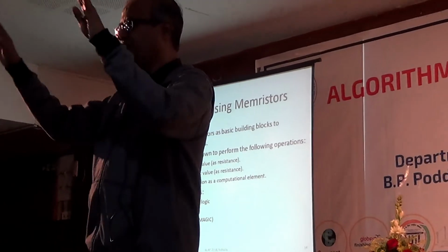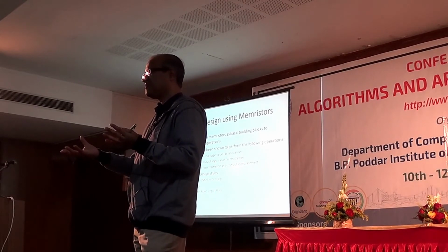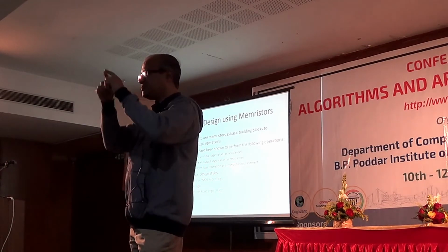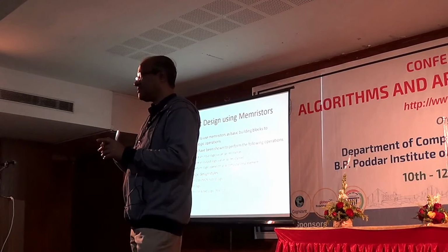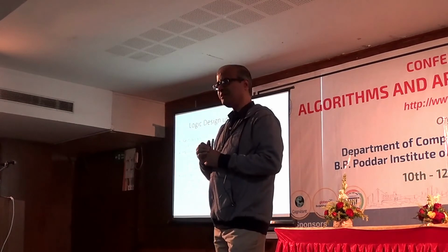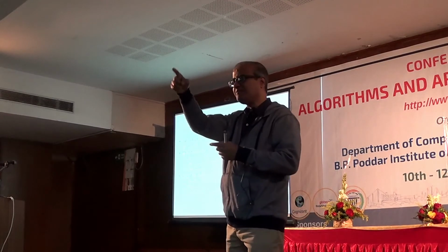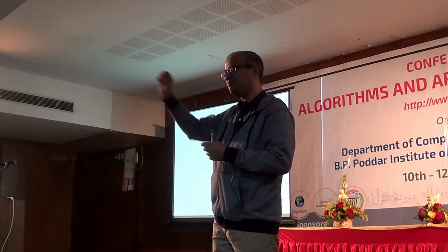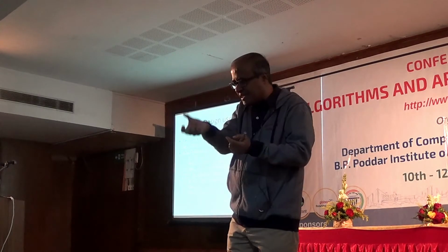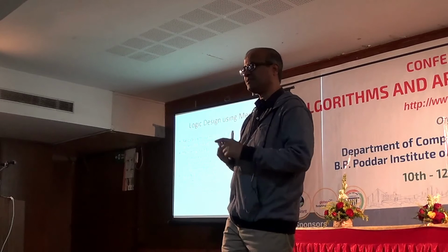Let's say when we design memory systems, how do we design? How are the memory cells organized? They are organized in a 2-dimensional array, very compact layout. So it is called a crossbar structure. There are rows, there are columns. So in memristor-based memory, there also we consider a crossbar-like structure, where the memristor devices will be sitting between every row and column, at the junctions of the rows and columns. Suppose I lay out the rows, then I fabricate the memristors. On the top, I lay out the columns, like that.